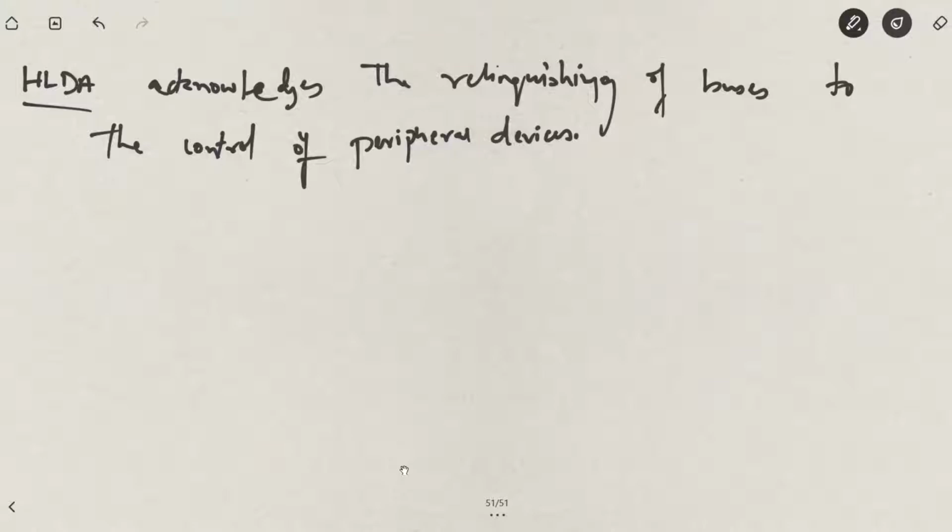In this case, the processing does not take place through the microprocessor. The external device directly accesses the memory by taking over the control of the data bus and the address bus. Only after this signal becomes low again will the microprocessor be able to take control back of these two buses. HOLD is acknowledged in the next machine cycle as soon as the request is made.